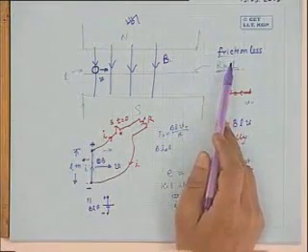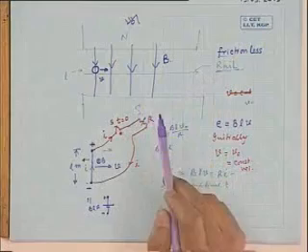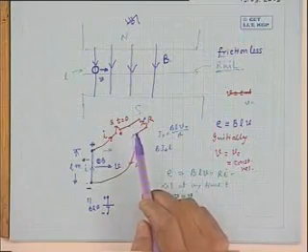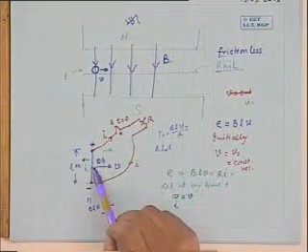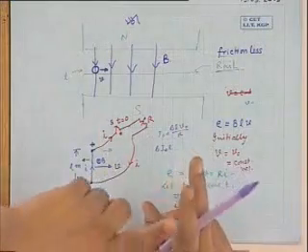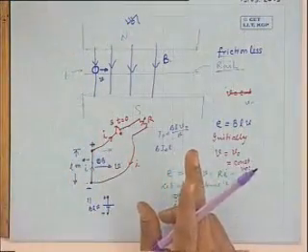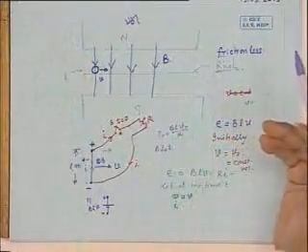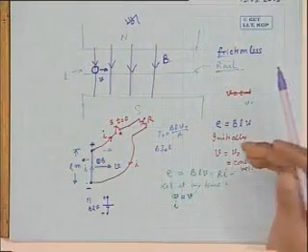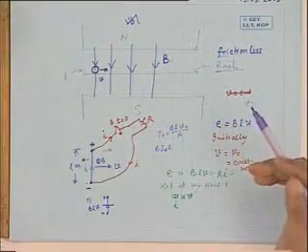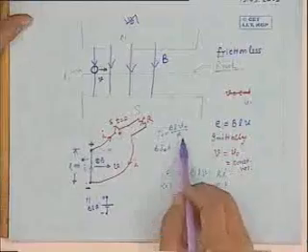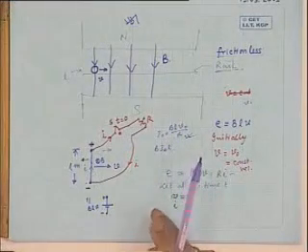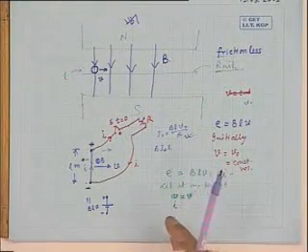In a practical generator, what will happen? Suppose there is friction present on the rails. Then even with this switch open, you have to give a little bit of force by the prime mover to the generator so as to make that friction force equal to your prime mover force. Of course, that opposing force is not due to electromagnetic nature, but it is inherently present on the track. Some small force will be there. Then you load it, then you have to increase this one. And another important thing you should note, that in a generator, both generator and motoring action go side by side.